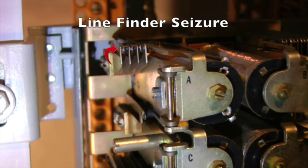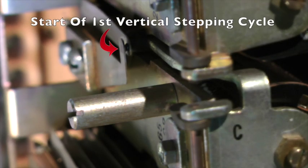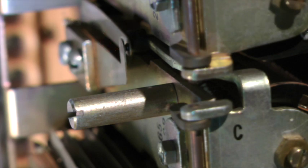The operated A relay provides operating and holding ground paths for other relays and magnets in the line finder, and remains steadily operated until the connection to the first selector has been established, at which time it releases for the duration of the call. The C relay is operated via its secondary winding by the operated A relay.